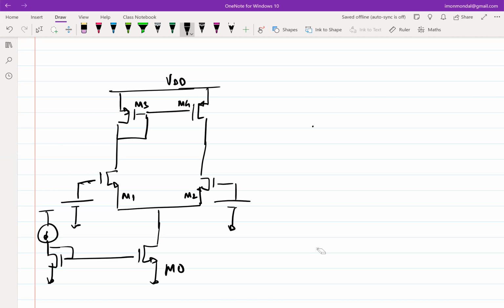So this DC voltage we were calling VB, or you can call it VCM, that is the common mode voltage applied between the two terminals. This is one way of doing it. You can put a resistor divider and then also bias. But the question is, will it have too much of an effect if this DC voltage varies slightly? In a common source amplifier, it was having a lot of effect, right? Because gm was changing, current was changing, all those things. In this case, will it have too much of an effect?